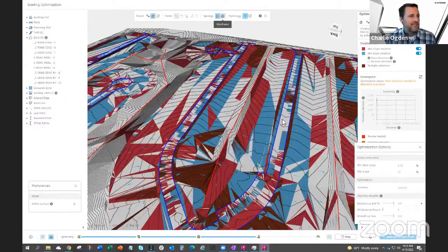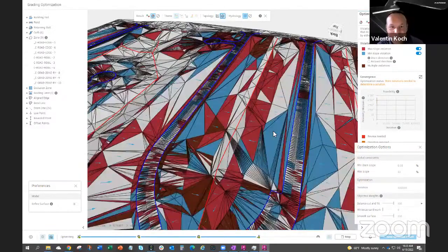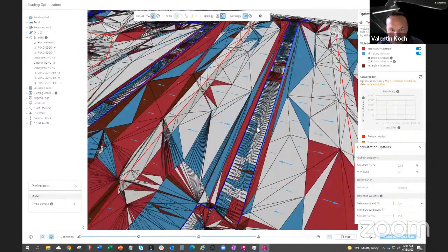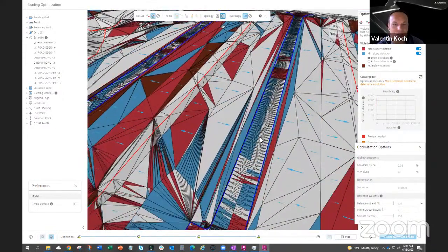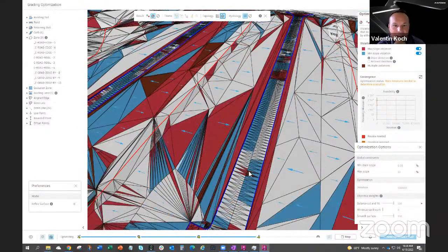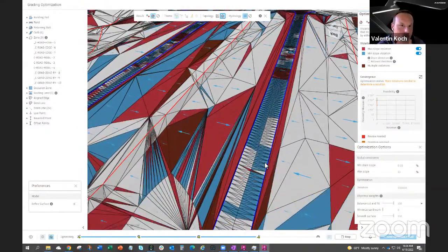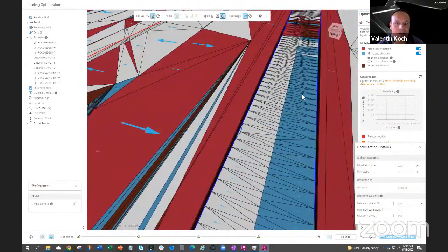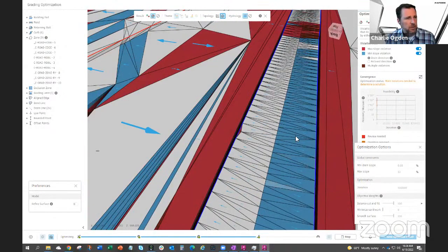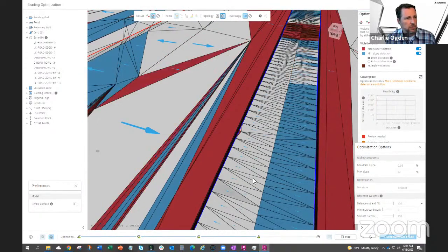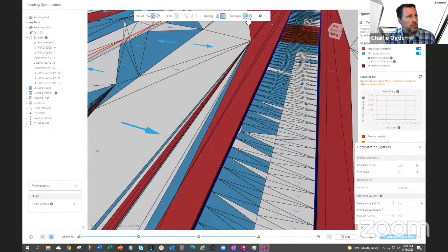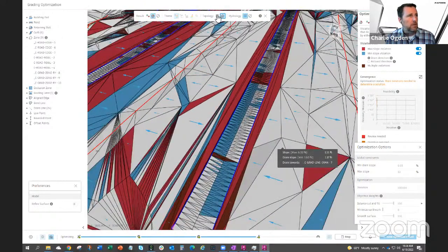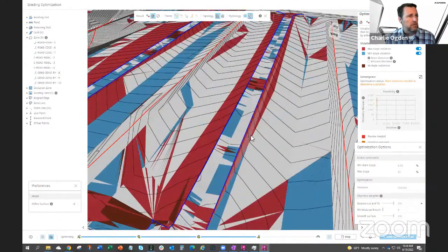You can see these elevation offset points that I mentioned on the road, how they create this triangulation. That's nice for getting our crown built. So you can go back to the contours and see the crown shaping there. And you can see it's trying to at least get the minimum slope towards the edge of the road. That's what the direction vectors here will show us. Contours, turn those off.